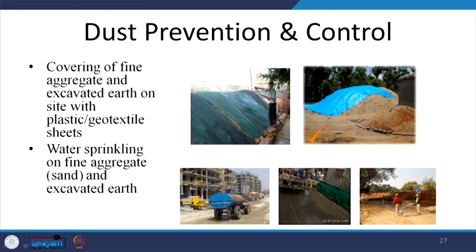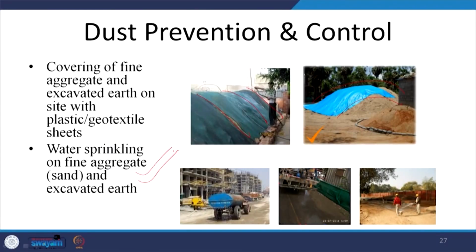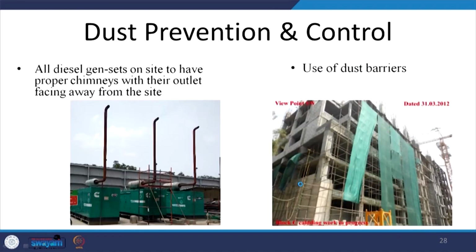In addition to that, coverage of fine aggregate. Here we can see that the fine aggregate and also the soil which is excavated and is available on the site is properly covered. Not just what is there on site, but all the vehicles which exit the site and carry a lot of construction materials need to be properly covered too, so that they do not carry dust with them. In addition to that, water sprinkling on the fine aggregate and excavated earth. Water will control the dust from rising up and creating problems.